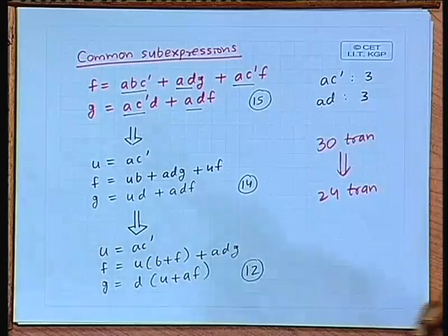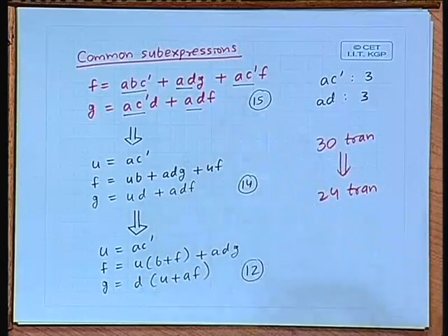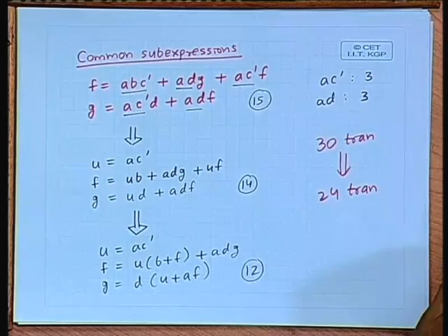Now in the method of espresso, there also the number of literals were used to estimate the cost of implementation, but in espresso the target technology was not necessarily CMOS. That is why there was some inaccuracy in the estimate of the hardware required, because they were concentrating only on the gate level netlist.